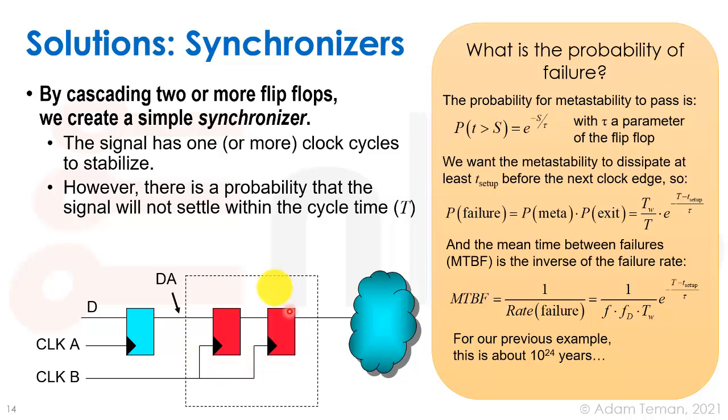But this clock signal is fine because it's going through a synchronizer. And synchronizers are often provided in the library as a single cell. So you'll get a cell that already has these two flip-flops in order not to cause skew between them and the clock net over here. If you just instantiate two flip-flops in your design, which is something that's commonly done in RTL, then you're going to route to these guys, and you might actually get a hold violation between these two guys, which is not something that you want either.